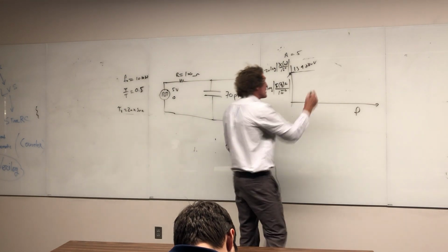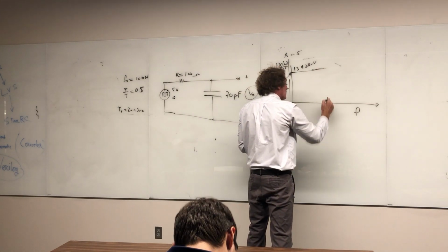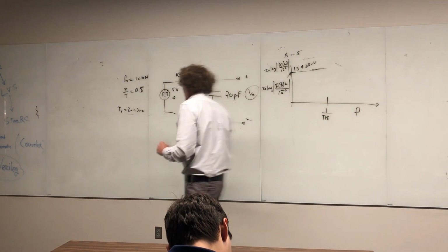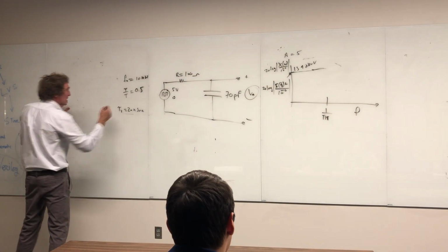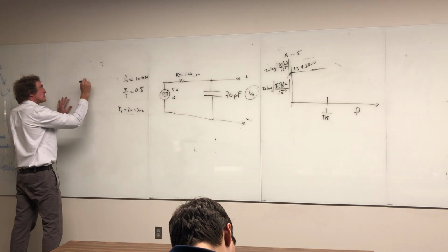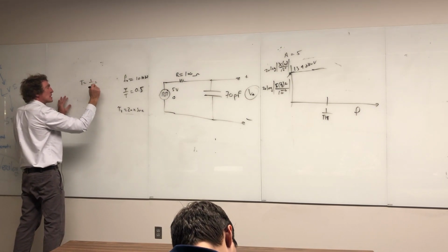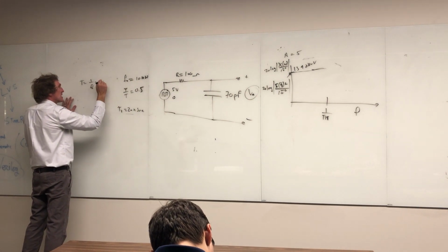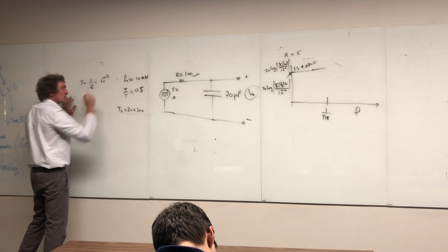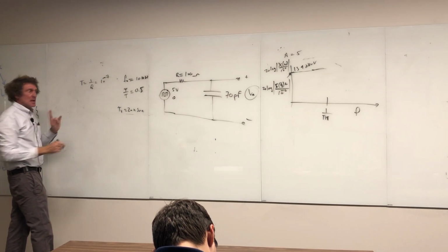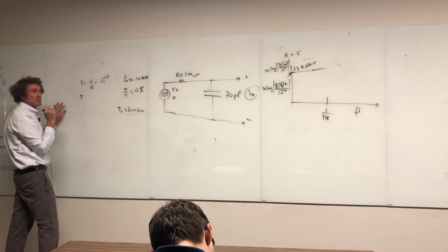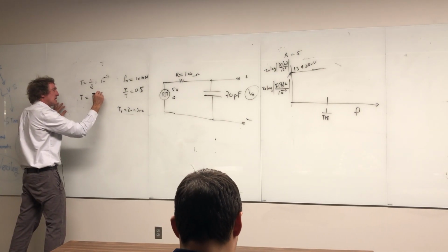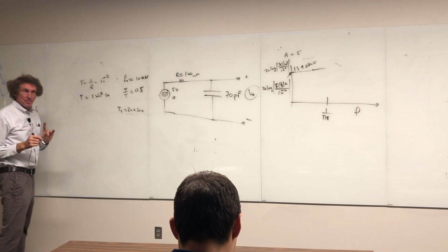Now, the first break frequency right here will be 1 over pi tau. So we've got to get tau. And how do we get tau? Well, look, T is equal to 1 over f naught, or it's equal to what? This is 10 to the 7th, so it's 10 to the minus 7th. Does that make sense to everybody? Seconds, correct? Now, tau is 50% of that, or it's going to be what? 5 times 10 to the minus 8 seconds. Do you all agree with that?